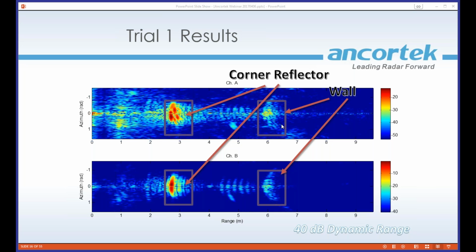I think it's 16 steps. I'm kind of embarrassed, I forget now. But essentially, I can move it in revolutions, or I can move it in steps, and it's down to millimeters per step, and it's very accurate. So I haven't actually had any trouble with using just the servo motor with getting distance information.